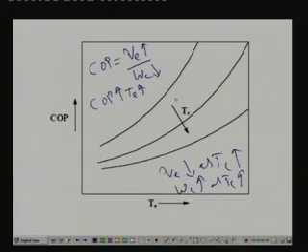So as a result, COP reduces as your condenser temperature increases. One thing you can notice here, just like your effect of performance on Carnot system, you can see that at lower condenser temperatures, the effect of evaporator is quite predominant. That means this curve is quite steep compared to other curves. So at lower condenser temperature, evaporator temperature has a larger effect, and at lower evaporator temperature the effect of condenser temperature is marginal. So, what do we conclude from this?